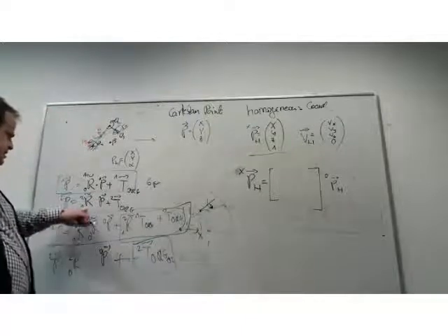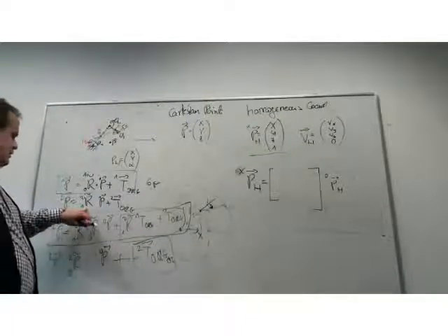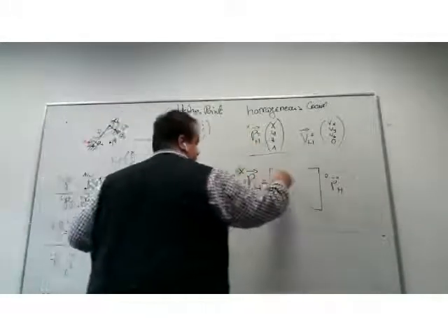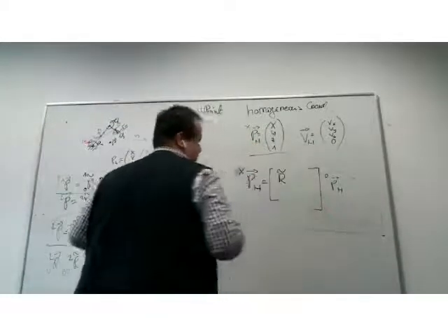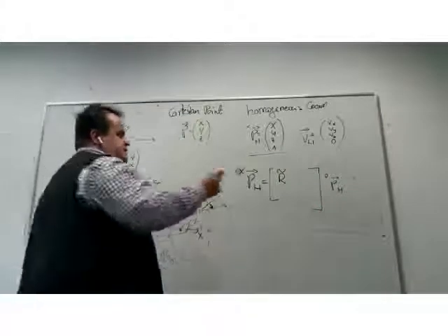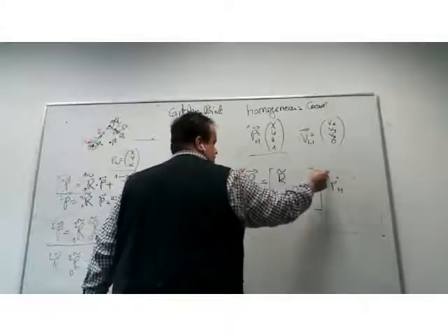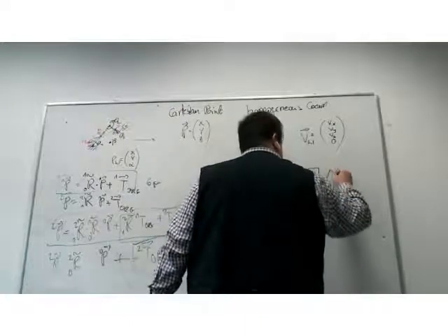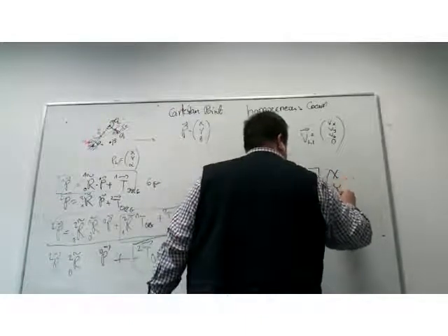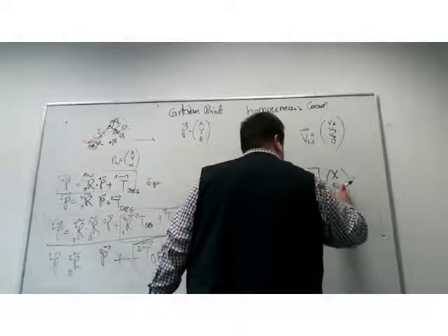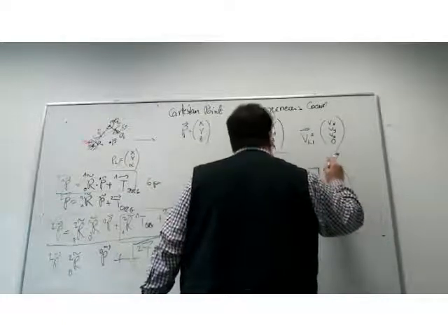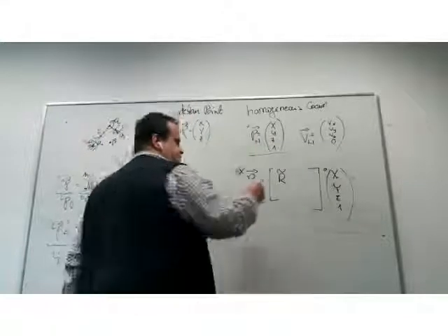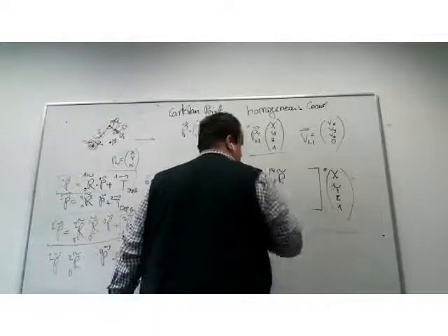So let's say in the first frame, it means I need to multiply the x, y, z component by the rotation matrix. Instead of writing P homogeneous, I could also write x, y, z, 1 in, let's say, 0. This is a rotation from 0 to x.